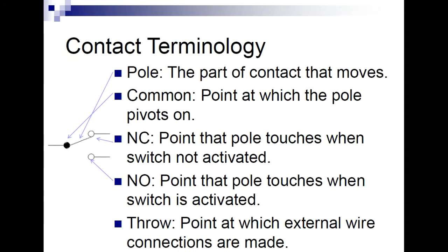So NC means that's the one that is normally closed, and so that's going to have a high voltage to it. Basically here we just have our voltage, whether it's a 24 volt DC signal or 120 volt if it's AC, or possibly for some sensors it may only be 5 volts or something. But it'll be a high voltage coming in here, and then that high voltage is being applied to the normally closed.